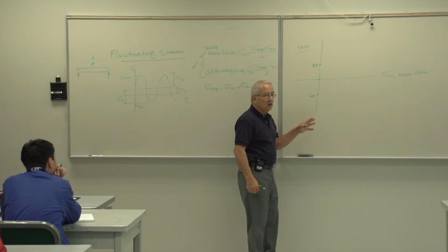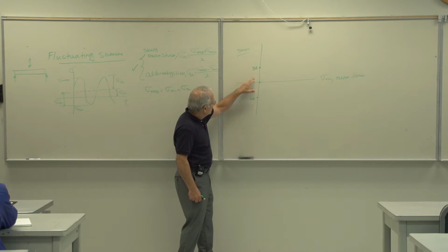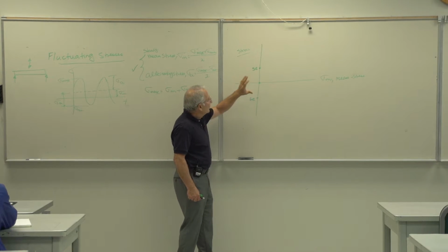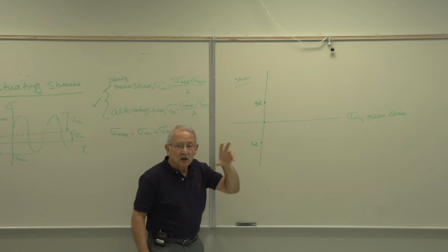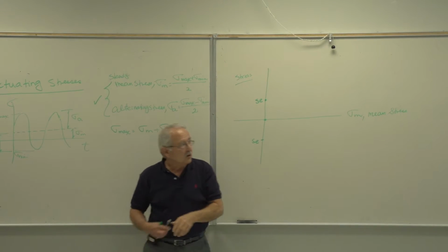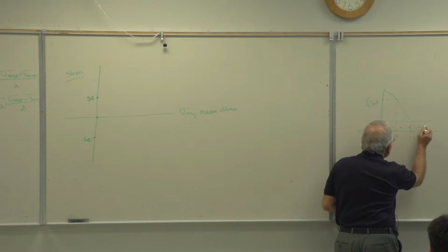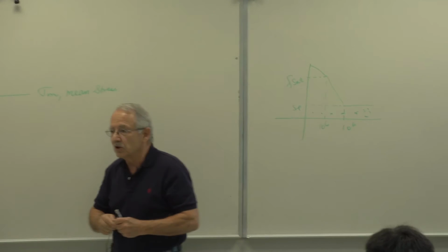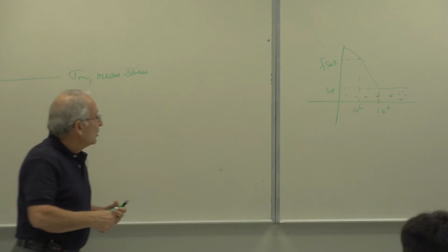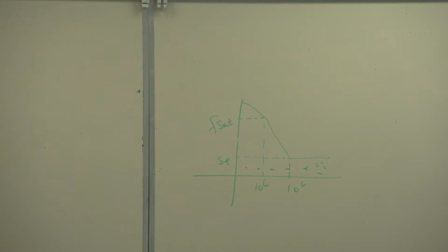If my stresses are smaller than this, in other words, they plot over here, before I get to these, I can expect infinite life. If my stresses are below SE, there's infinite life. Stresses above, there's finite life. For the time being, I just want to look at infinite life.